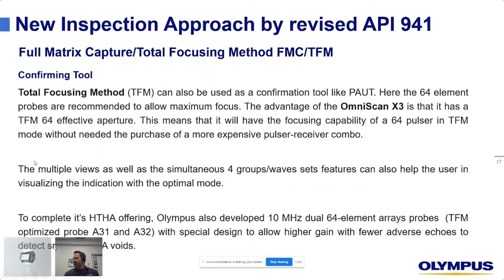For the purpose of this call and further demonstration, I'm only going to be using one wave set at a time, but you can program more than that and have the input of various wave sets, various TFM modes, basically. To complete this offering, and I will also demonstrate them later, we also have a complete line of 10 megahertz probes that are pulse echo as well as pitch-catch through dual linear arrays.